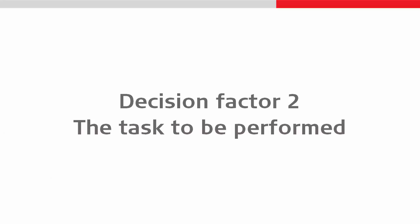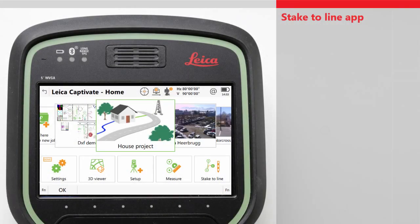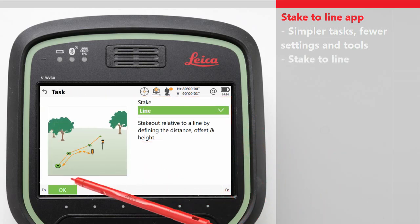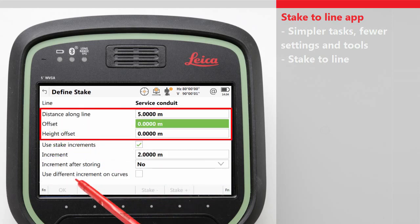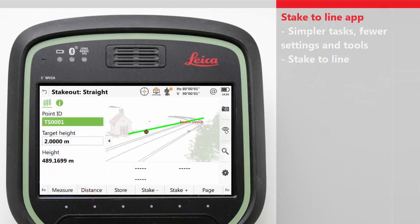Let's now look at the second factor which defines which app to use. This is the task to be performed. The stake line app allows a number of relatively simple tasks to be performed. I will only describe a few of the tasks and the basics here. Other videos will give more detail. Firstly, we need to choose the task. The stake to line task allows the line to be selected, the distance along the line, the offset from the line, and the height offset of the location to be staked. If needed, the distance along the line can be automatically incremented. And of course, the staking of the location.